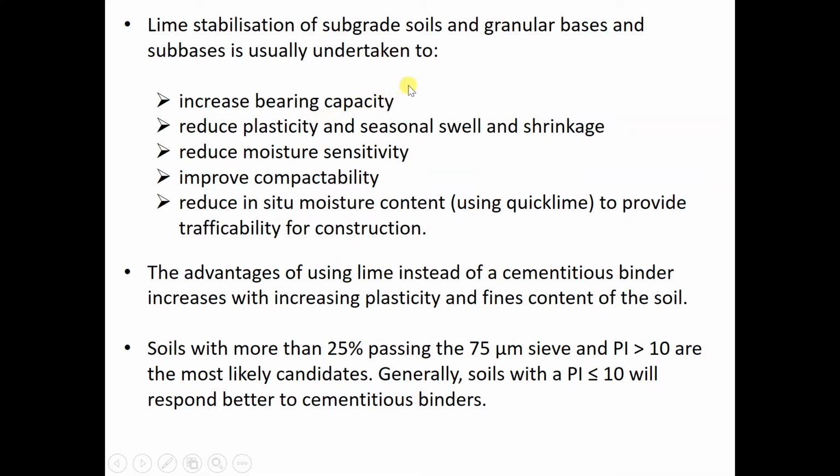Lime stabilization of the subgrade soil and granular beds and subbeds is usually undertaken. So, what are the purposes of the lime stabilization? There are five of them. First, to increase the bearing capacity, mostly for the base or subbase with high plasticity, like a plasticity index of more than 10%. Secondly, to reduce the plasticity and seasonal swell and shrinkage.